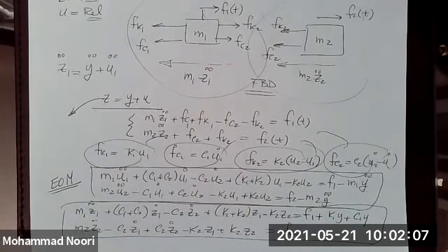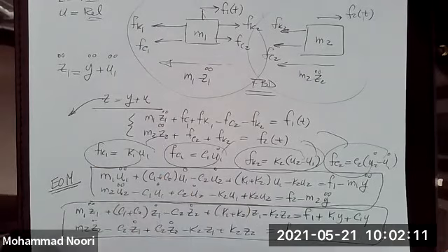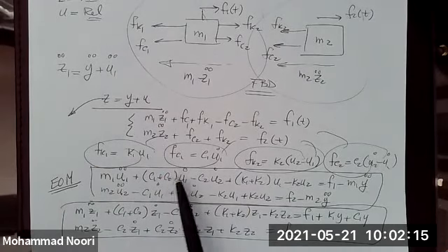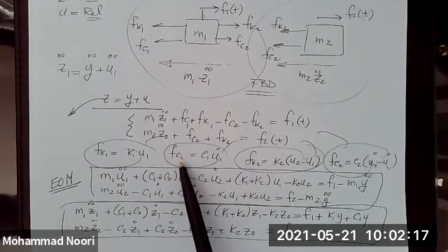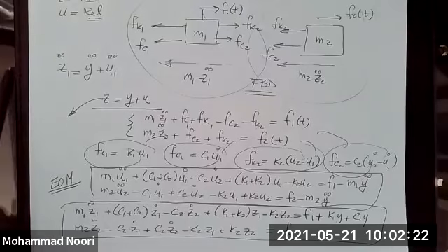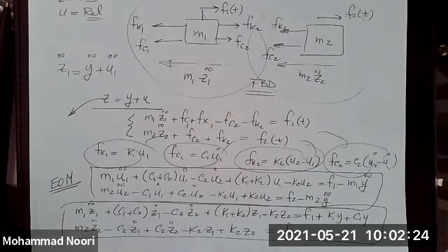We need to find a different coordinate system that you would transfer these two into. And there, these equations would become decoupled, in terms of new variables, new coordinates, that we call modal coordinates. You solve for the displacement in that coordinate, and then transfer those back to find U1 and U2.